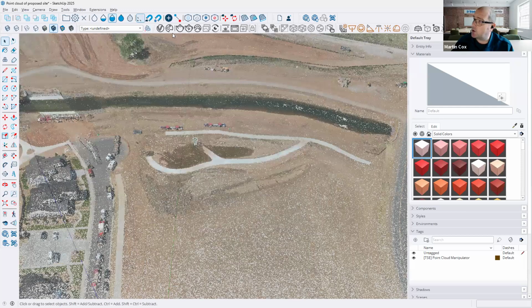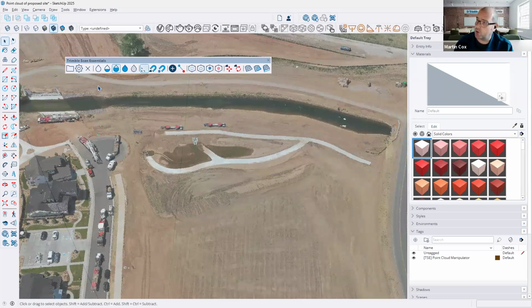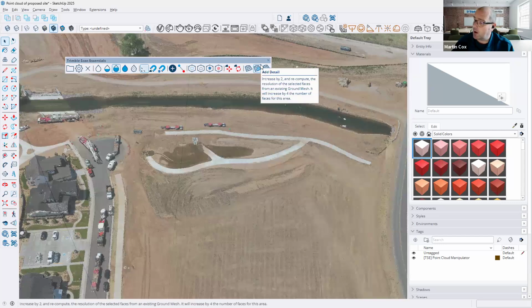And we have an entire menu within SketchUp for Scan Essentials. And I can bring that one down here just to show you, so it's nice and clear, the tools that you have. Just load in a scan point cloud. I can manage my point cloud. I can unload it. I can choose how visible it is, so if it's 75% transparent, I can turn it off completely. I can choose if I want to snap to those points, set construction points and guidelines, and also clip our point cloud, but also turn it into a solid as well.